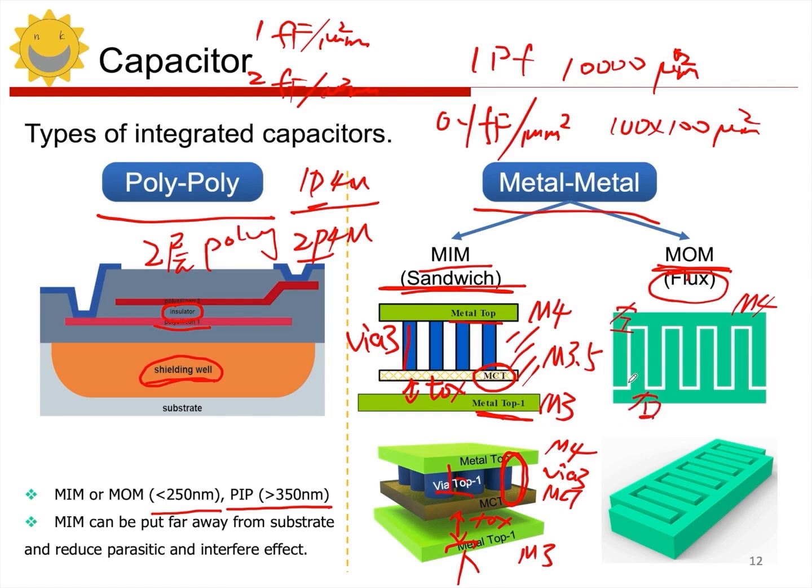So how is the capacitance formed between them? It's based on the gap in the middle, right? The dielectric layer, right? What is this? It's the oxide, and it's formed by this material. Now, where is the metal plate? The metal plate is on the side of this wire, on the sidewall, right? We've talked about how this sidewall has a certain thickness. So once you draw this interdigitated structure, the area of the expanded sidewall is relatively large. Therefore, when you consider its equivalent, the area of the capacitor plates is quite large. This is how the capacitor structure is formed, through this method.